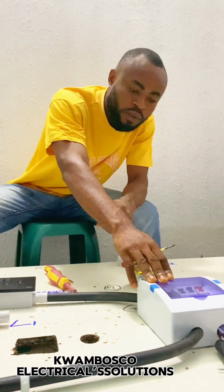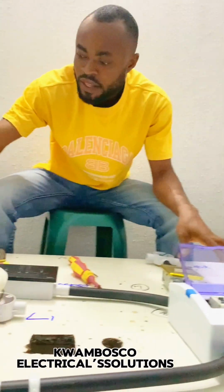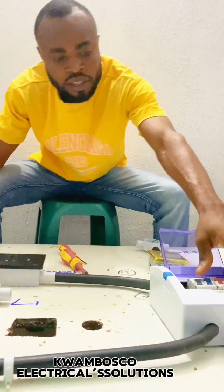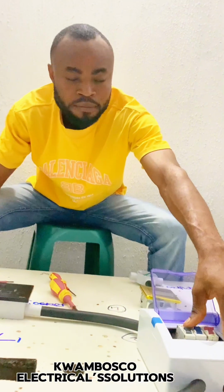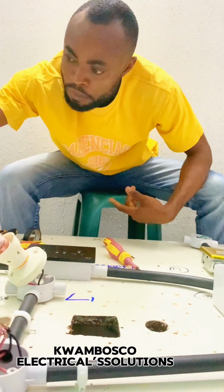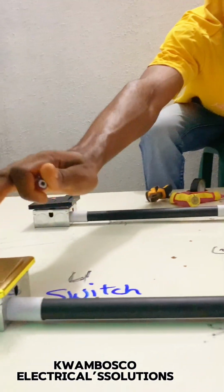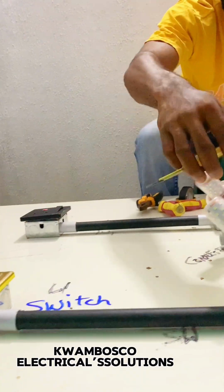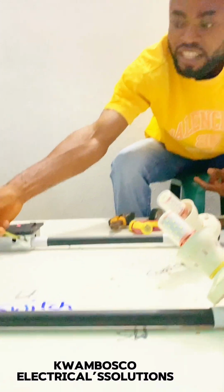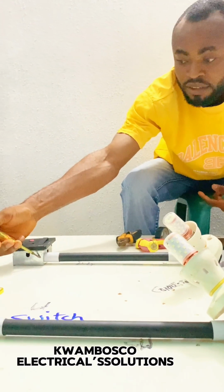This is our distribution board. Every one of these sockets, this circuit here, has its own breaker here. So now you come to your distribution board, you switch off the circuit breaker you touched, you come back again and test it. Okay, this circuit breaker is for the lighting point. Now this lighting point is not the problem, the lighting point is okay, but we realize that the socket is still bringing out light. That means the fault is still here.